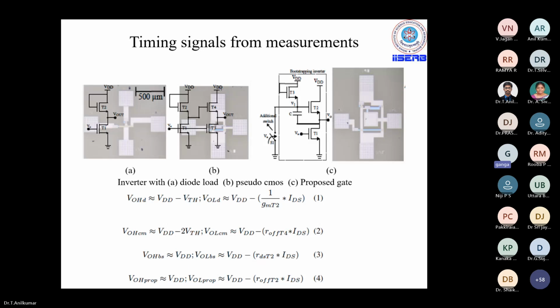It looks simple here, but when the signal needs to be propagated through many logic gates, every gate is going to introduce a VTH drop. So for example, say it is transmitting through 5 stages or 6 stages, meaning 6 times VTH drop is going to be there. So after the 7th stage, we can't really see the logic high level.